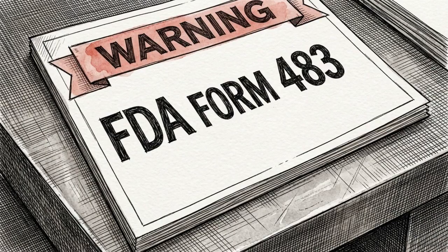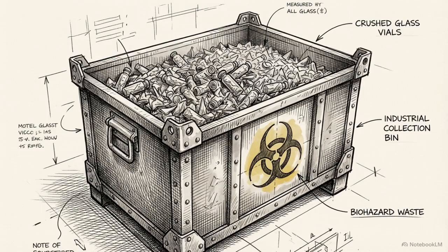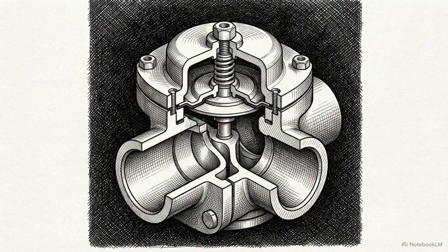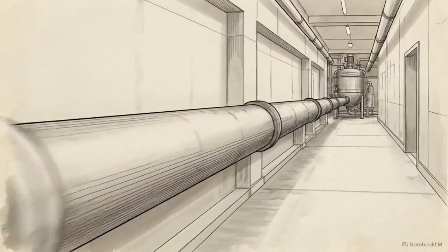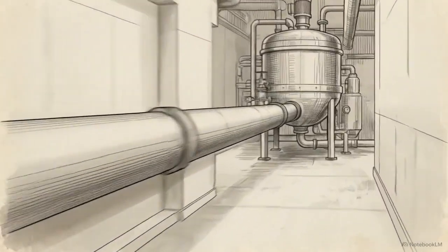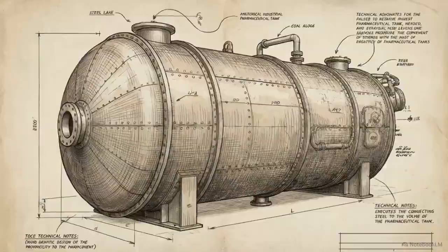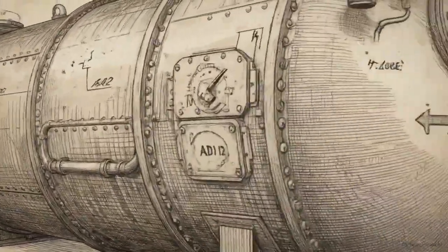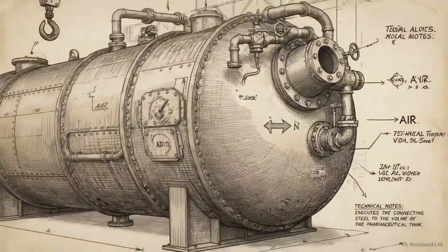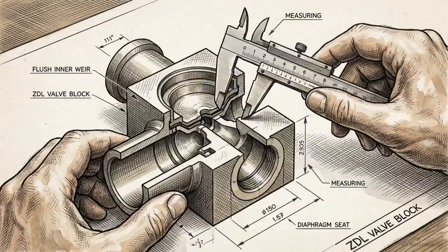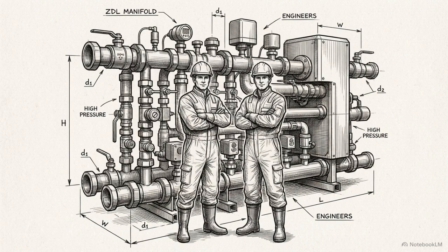The financial stakes are absolute. A single contamination event traced to a dead leg will trigger an FDA 483 warning letter and force the immediate scrapping of multi-million-dollar formulation batches. ZDL valves guarantee process integrity at every critical juncture, maintaining absolute purity from the distillation unit down to the exact point of use in the formulation suite. Assessing your own facility's dead leg risks against the latest ASME BPE guidelines is a necessary step for modern compliance. In high-purity manufacturing, the zero dead leg valve is the foundational engineering standard that separates a vulnerable system from a scientifically unassailable one.